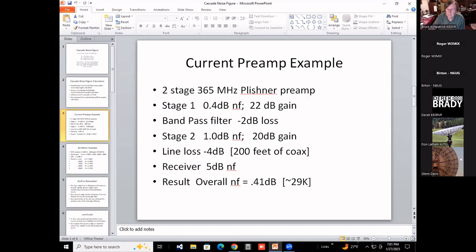So it just turned out that I wanted this noise figure and gain combination to be fixed, and we could change filters simply. These are very wideband amplifiers, so by using a bandpass filter, I restrict it to keep other interfering signals from causing intermod problems.